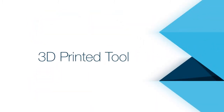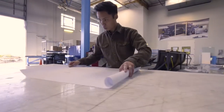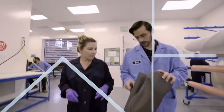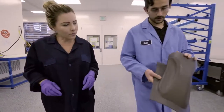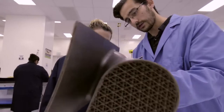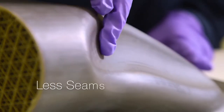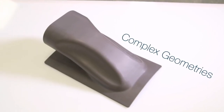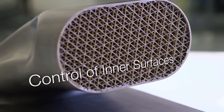The utilization of additive manufacturing in the context of composite fabrication begins with an idea which leads to a design in a CAD program. Once the design is complete, we have the tool 3D printed. Additive manufacturing allows us to have parts that have less seams, less post-production work. We're able to fabricate really complex geometries and it gives us control of inner surfaces of parts that we might not have if we were using a multi-piece tool.